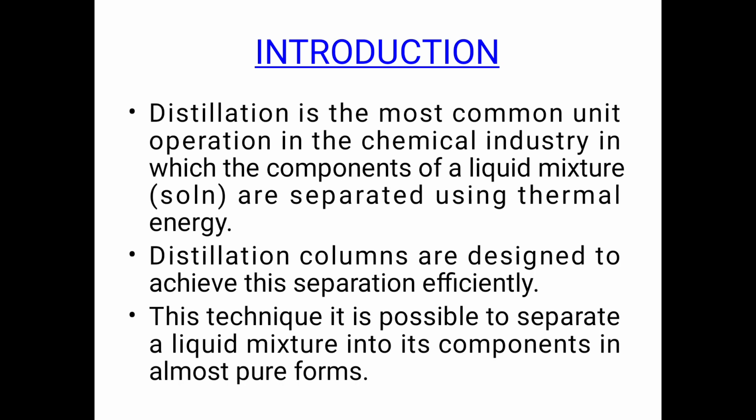So, an introduction to the distillation process. Distillation is the most common unit operation in the chemical industry, in which the components of a liquid mixture, that is a solution, are separated using thermal energy. Distillation columns are designed to achieve this separation efficiently. With this technique, it is possible to separate a liquid mixture into its components in almost pure forms.